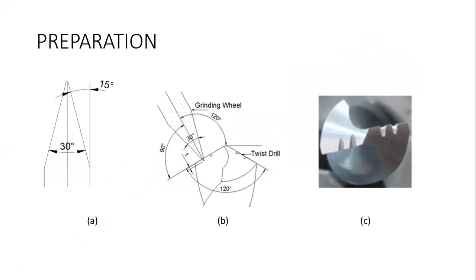In preparation, the first step is to make a splitting nick on the cutting lips of the drill bit with a universal tool grinding machine. The drill bit specimens in this study are uncoated drill bits with a diameter of 14 millimeters. The grinding stone used has disc-shaped aluminum oxide abrasive granules.